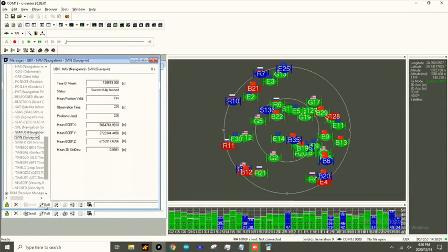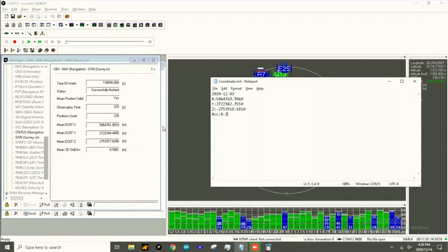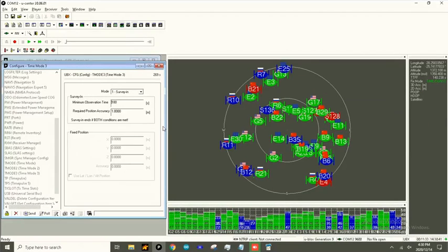And there we go. There is the survey completed after 225 seconds. We have reached a standard deviation of 0.99 meters. So clearly this was the restrictive controlled criteria until we reached a satisfied solution. So we can copy these coordinates to a text file, and I have already done so with a previous example, just noting the date and when these values were recorded alongside the typical accuracy that was achieved during the survey in process. So now we know the exact position of the antenna.